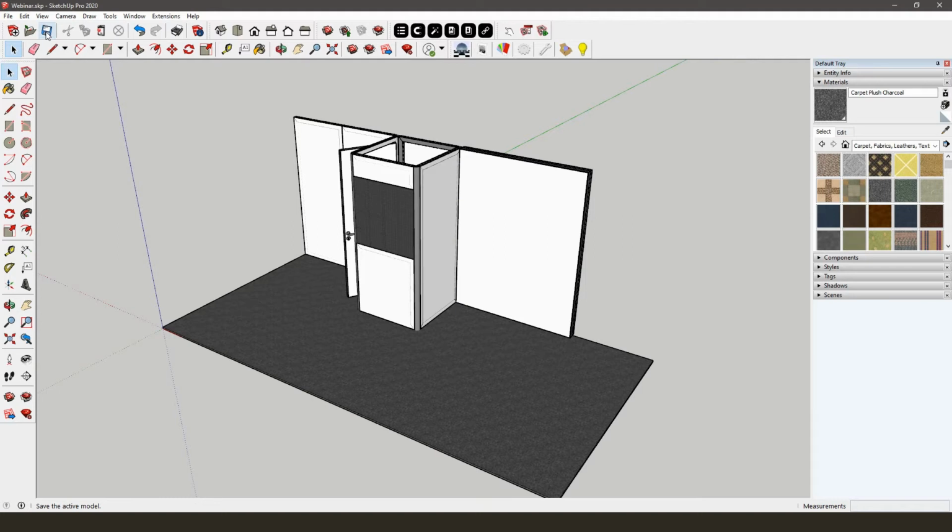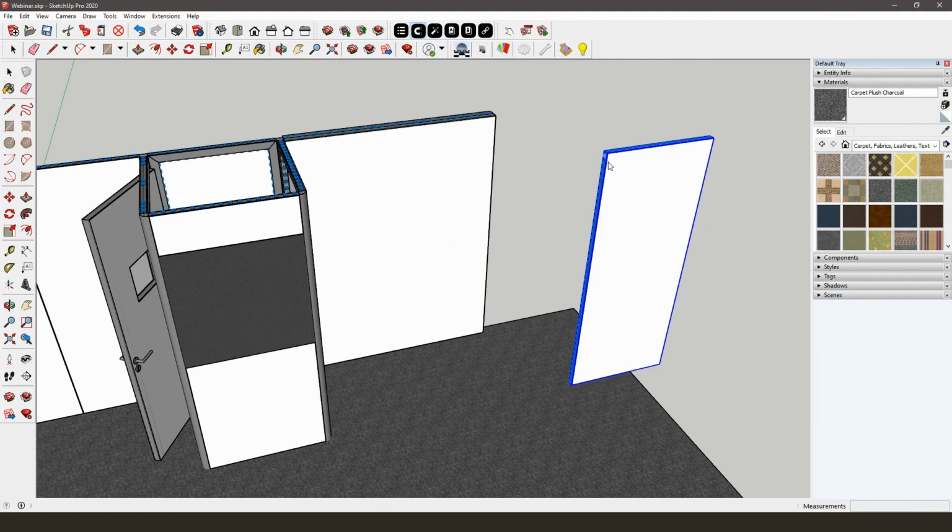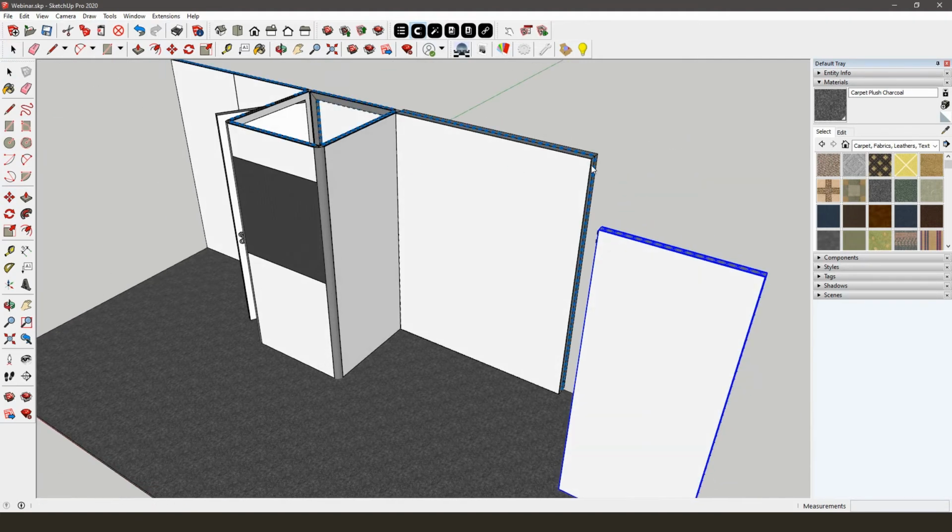We'll now add an arch section next to the Poly 124 bright lightbox. Put a 39 by 95 inch Omni 55 frame next to the Poly 124 bright lightbox. You can copy the frame using the Move tool and the Control button. You can easily put your frame next to the lightbox using the Aluvision snapping tool.